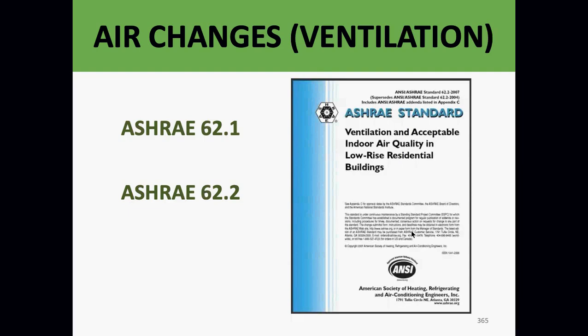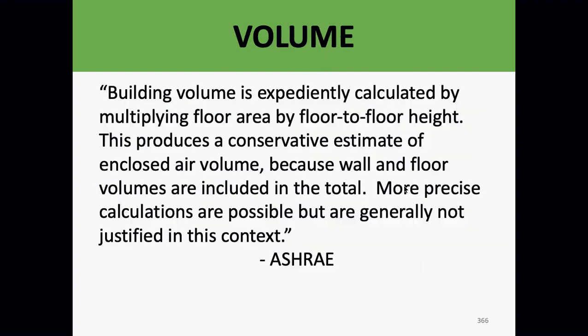ASHRAE publishes a guide. You can find it online. I'll give you some numbers as we go through the rest of this course, and I may actually throw a chart up there, but there are ventilation standards specifically designed for residential, commercial, different uses, and different parts of a building. This has all been thought out by the engineers. You don't need to recalculate this stuff.